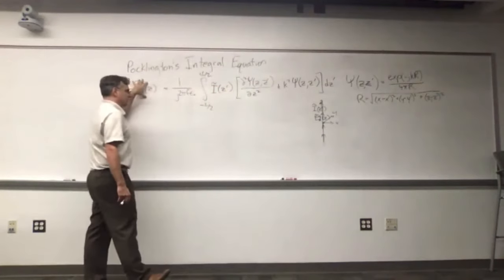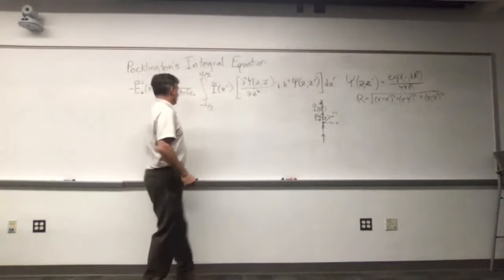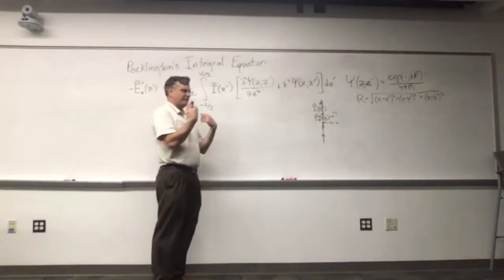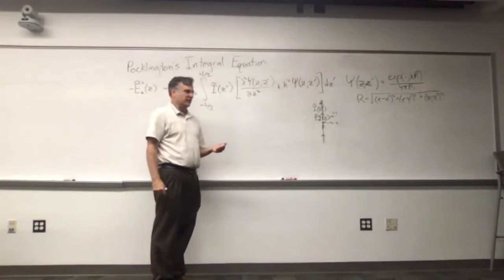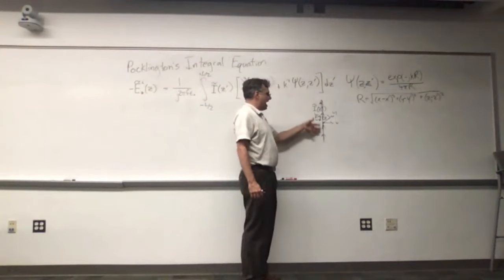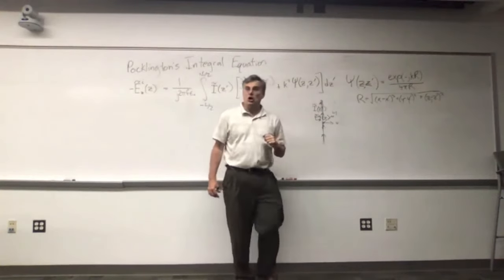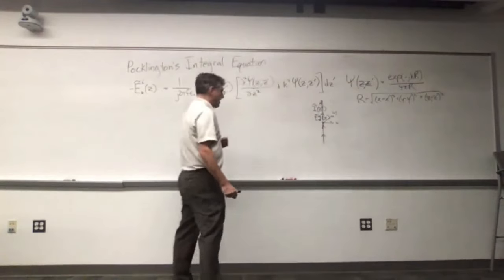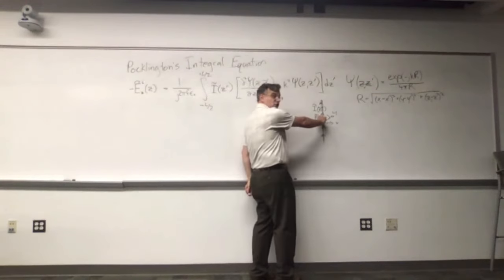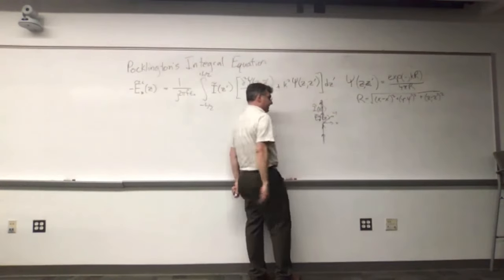This is your boundary condition. This is your integral. The I means an impressed field, a field that you have put onto the element. So for example, if this was a half-wave dipole, our I as a function of z prime is unknown. However, our excitation would be a voltage right in the middle of the thing, right? That's where we usually excite half-wave dipoles or dipoles of any nature.